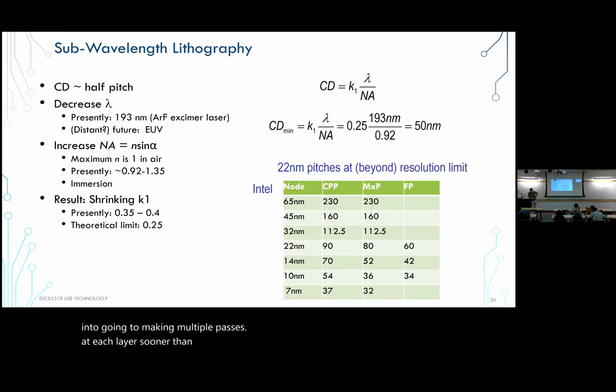They encountered various sources of variation as a result, and the well-documented 10 nanometer node yield issues. If they had just relaxed it by 10 nanometers or so, or 5 nanometer pitches, everything would have been easier. But they bet at that time that the lithography was ready, and it was not. And that cost them 2 years.